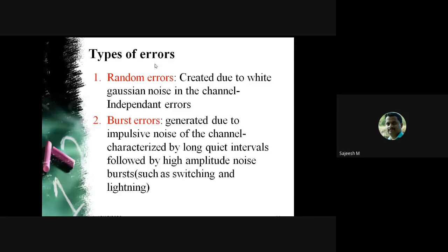Therefore, if the message is 000, then 0 is added. The code word is four zeros. Then 001, an extra bit is added. 1 is the check bit, parity bit. Therefore, the code word corresponding to 001 is 0011.